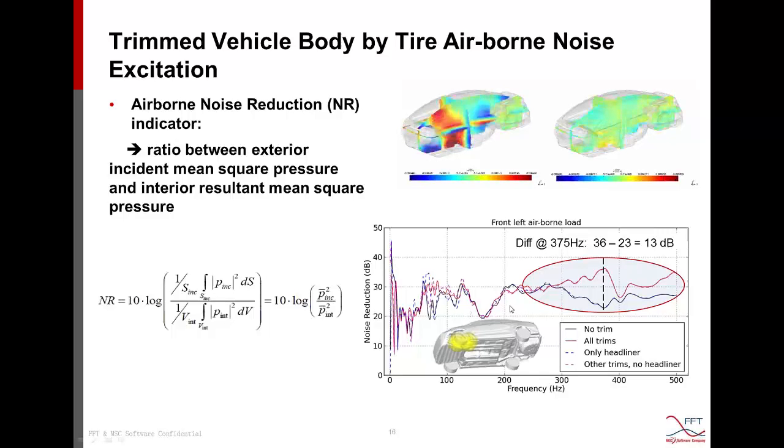Okay, so we can see here the treatment has quite limited effect below 300 Hertz, but starting from 300 Hertz, we have an increased noise reduction, as we can see here, when all the trims are taken into account. We have this difference of 13 dB here at this frequency of 375 Hertz, and here this is an animation of the pressure field inside the cavity at this frequency without and with the acoustic treatment.